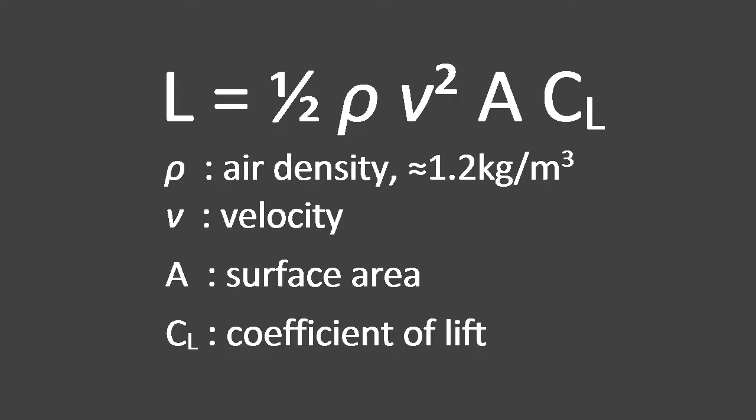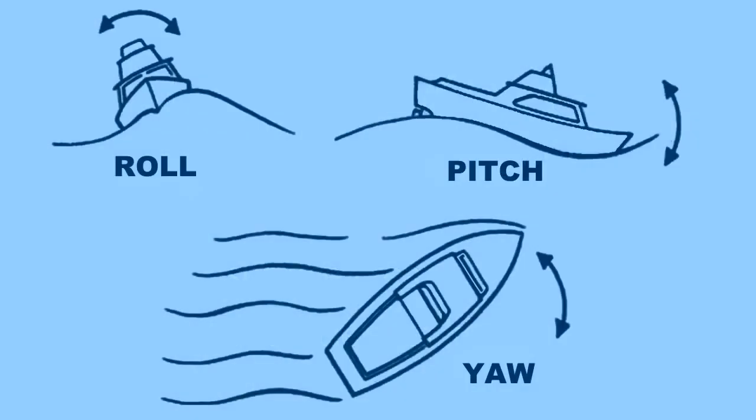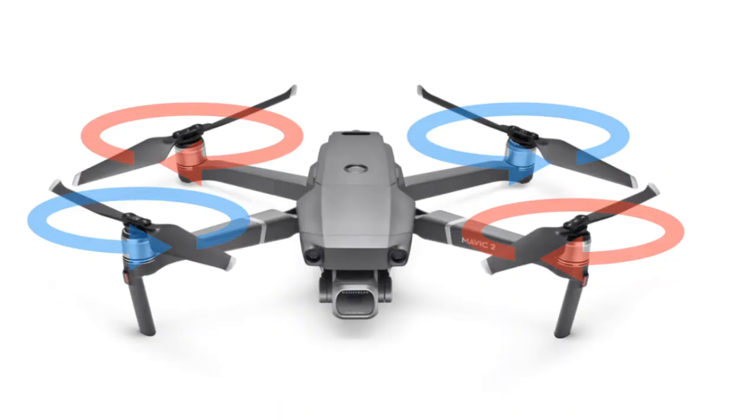Drone movement in the 3 axes, as for aircraft, borrows from naval terminology. Rolling is from left or right as viewed toward the front of a boat, pitching is the front moving up or down, and yawing is the boat pivoting or turning toward the left or right. The 4 motors and blades are divided into 2 sets. One set will rotate clockwise and the other will rotate counterclockwise.